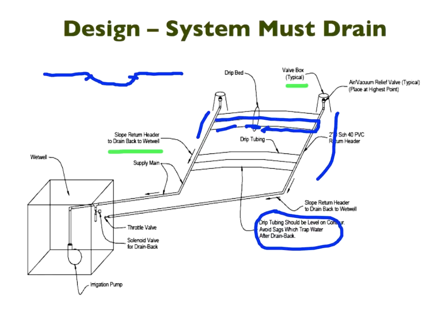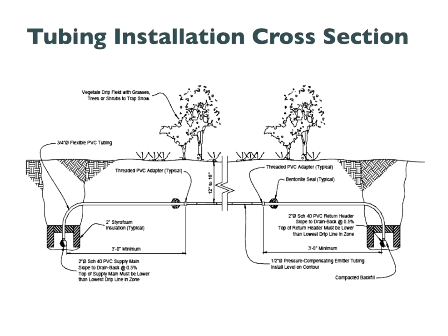And the same, of course, backing up there. So in actual fact, that frozen spot will be getting comparatively warm water from both sides, and it's not going to stay frozen for very long, and the inefficiency of the system will be absolutely insignificant. But it's better not to deliberately have it sag.